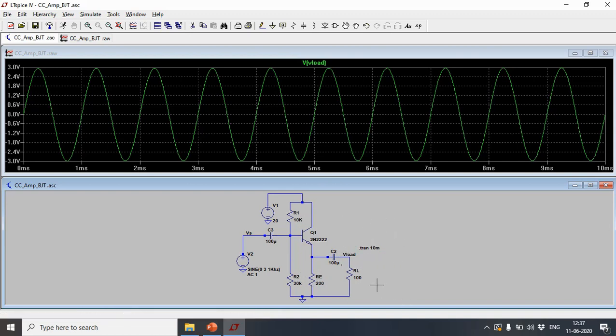If you're not going to have a resistance less than 1k, then you might design accordingly and keep the minimum power requirement here. You'll also have to see whether in this particular condition this transistor can sink that much current and dissipate that much power. These are all the design issues which you have to be careful with. Now let me get into the cascade stage.